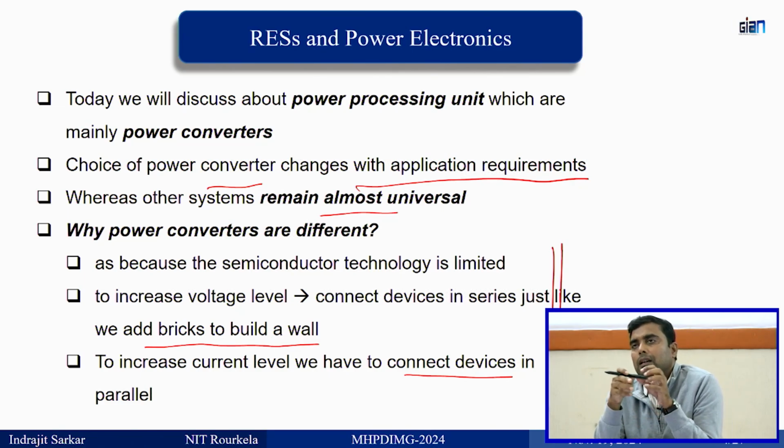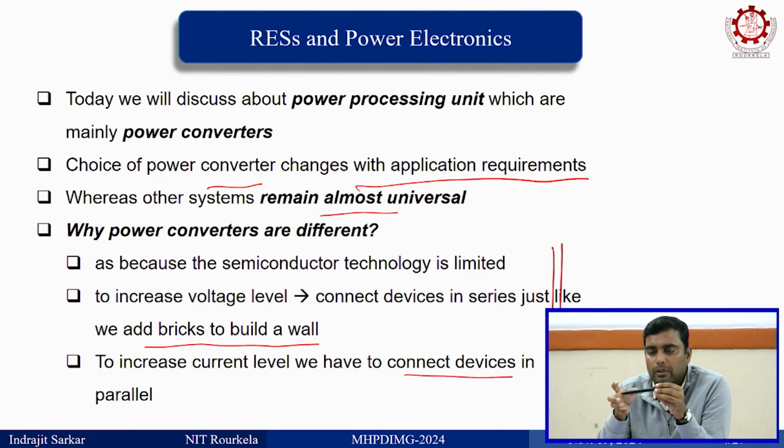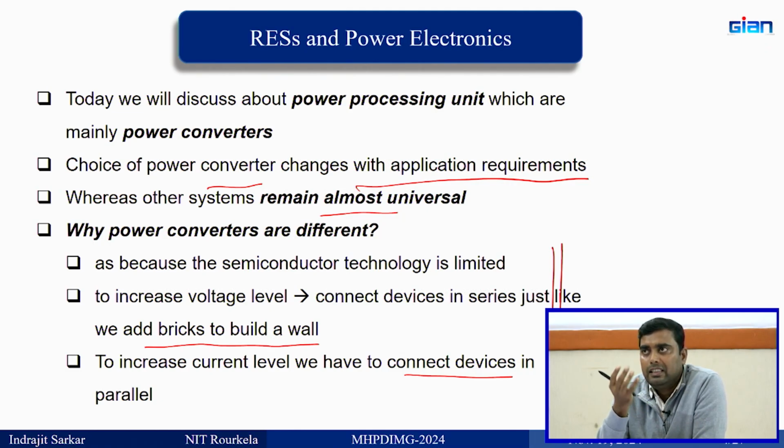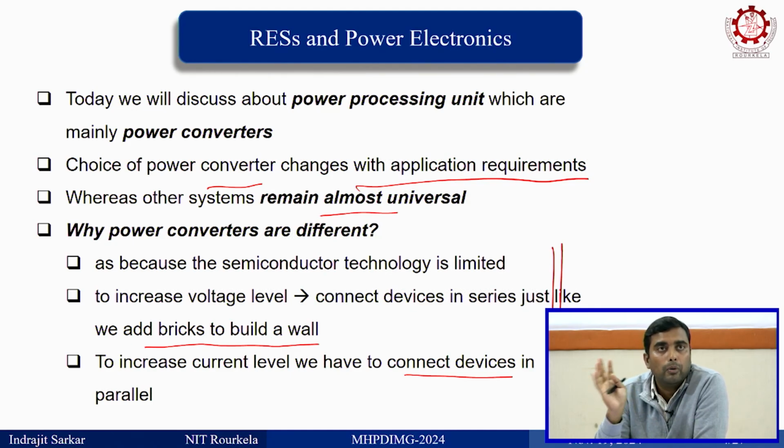Now, I can tell you about the legacy system; I have the slide for it. Thyristor is one of the very reliable, high power electronic devices, though people go with IGBT or MOSFET. For high power we don't go with MOSFET, we go with IGBT or IGCT. But in previous days, thyristors were the only solution for high power applications.